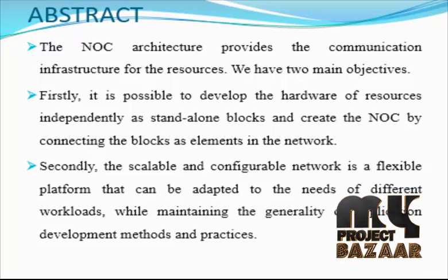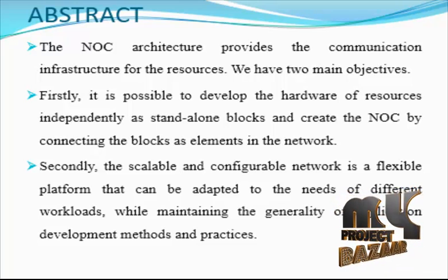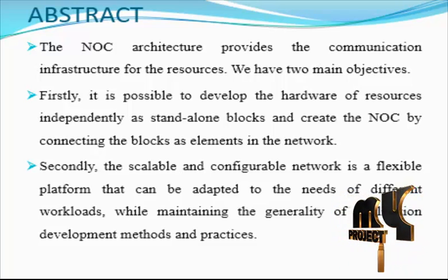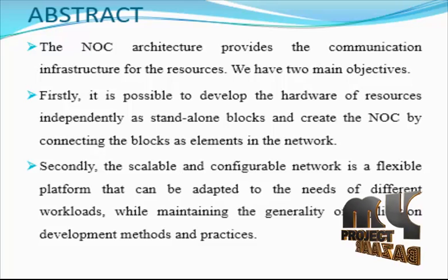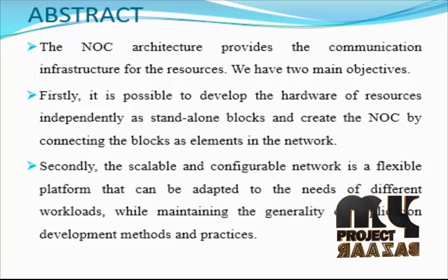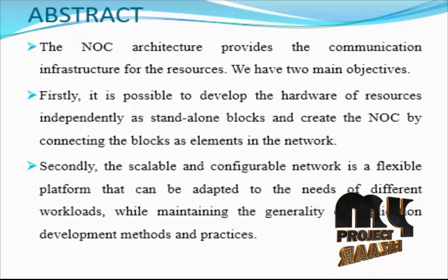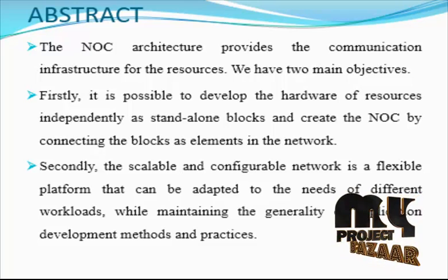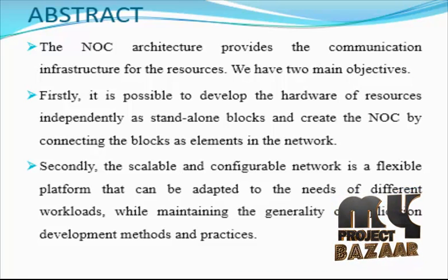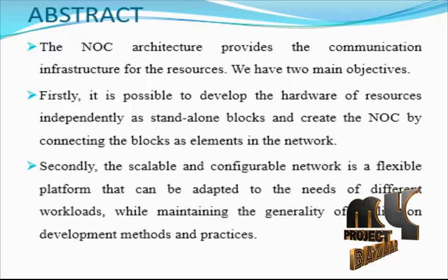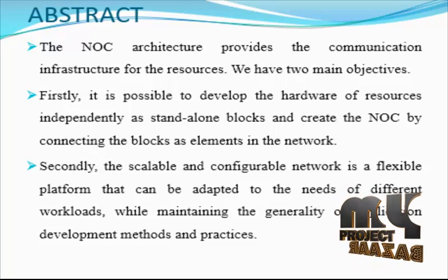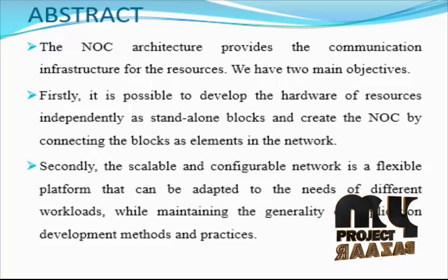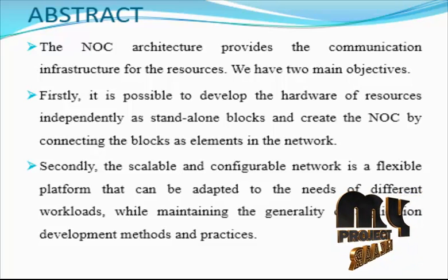utilization. We evaluate the area and performance on FPGA implementations of the overall process. Additionally, we illustrate the MACS low average channel setup latency using 6 network traffic patterns and 8 parallel JPEG decompression core trace simulation. Systems on chip are composed of multiple processing elements that are typically assembled in an application domain specific architecture with an inter-processing element communication network to enable the processing elements to carry out the application task.